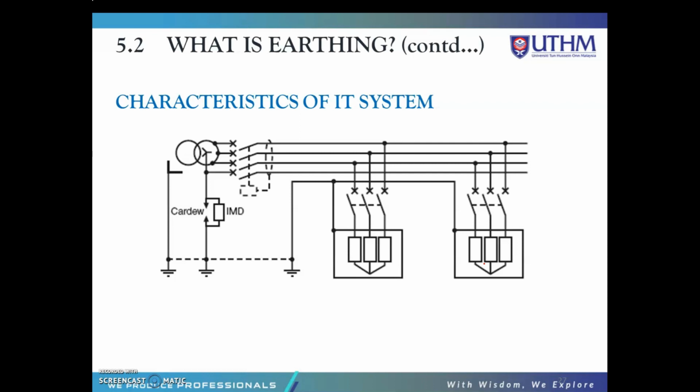It is generally used in installations supplied by a private medium voltage or low voltage transformer. It requires maintenance personnel for monitoring and operation, and requires a high level of insulation in the network. It implies breaking up the network if it is very large, and the use of circuit separation transformers to supply loads with high leakage currents.